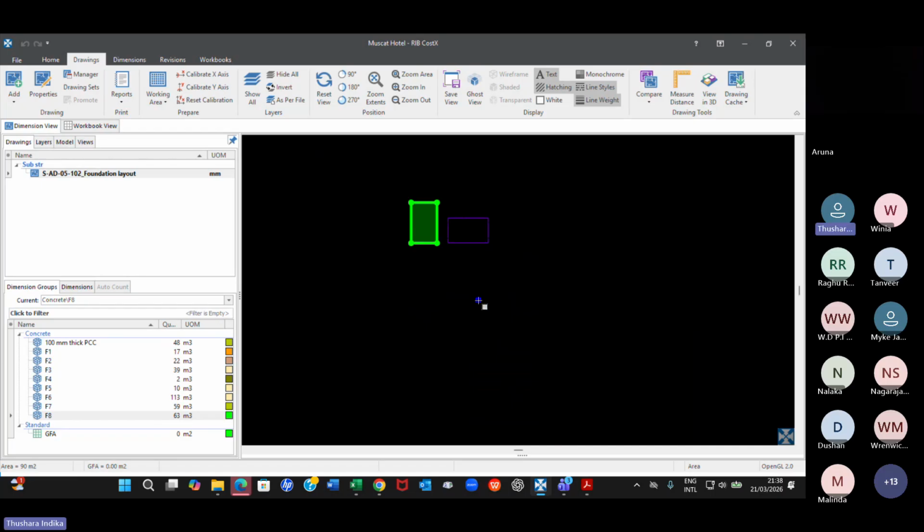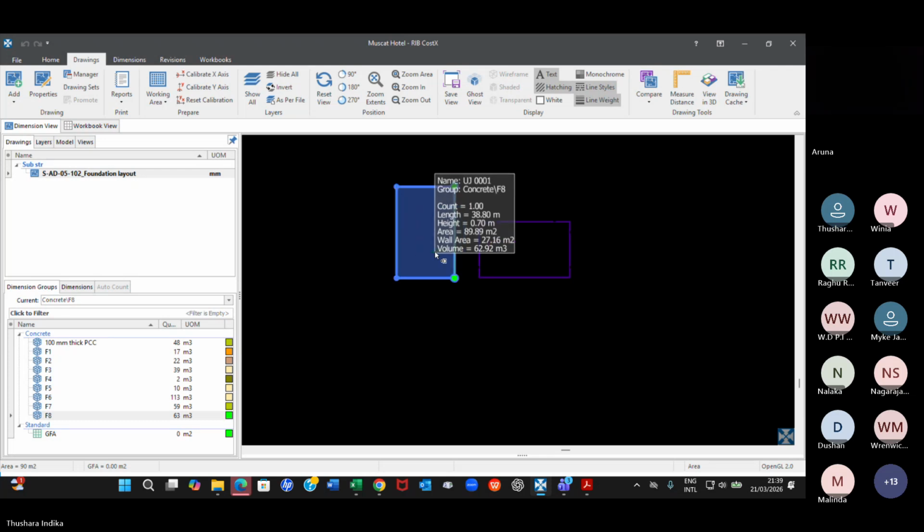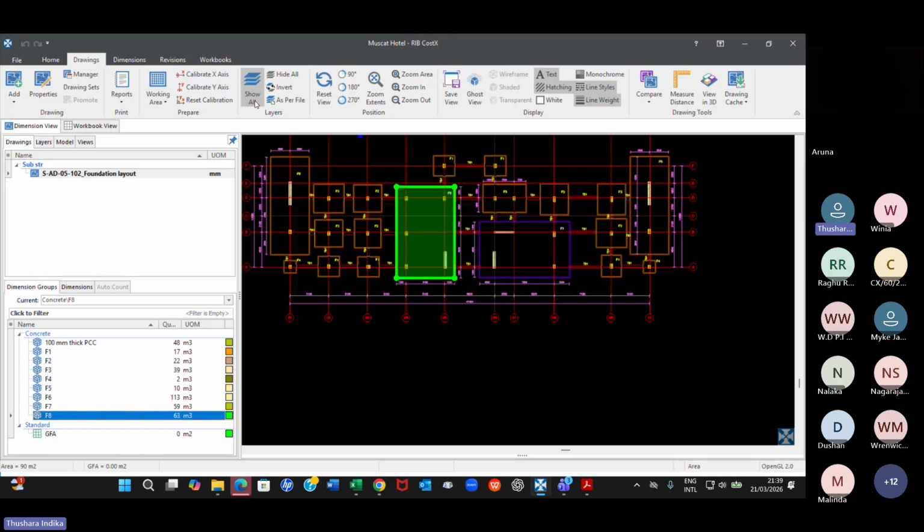So, but beauty is you can avoid all the unnecessary line when you measure certain element. Right, so using the invert function, that is very, very important function here. So that's why we can use that special shortcut, shift and mouse to measure the area. Right, you bring your mouse inside and then press shift, you get the area selected. That is very important functions. For that, you need to avoid all the unnecessary lines. Now we are back to normal, right?